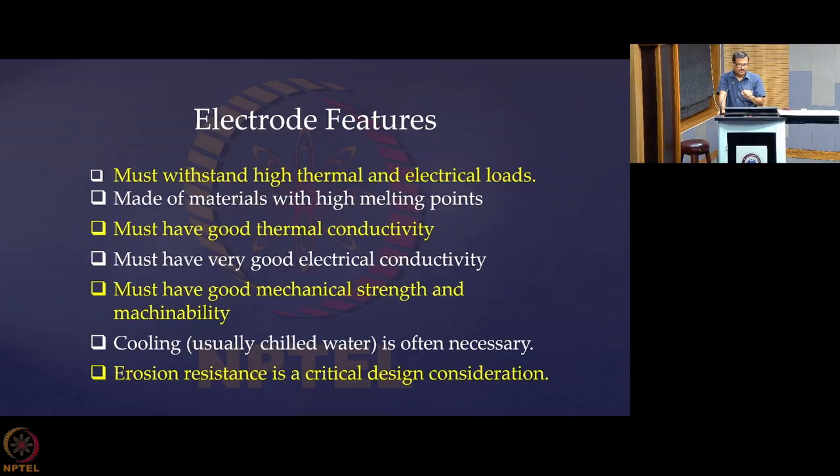That is the way it pits over the electrode surfaces, and such pitting causes erosion, and over a long time the complete electrode gets eroded, and once it gets eroded, the eroded structure itself allows you to concentrate the electric field lines over the sharp zones, and that allows further erosion of the material.